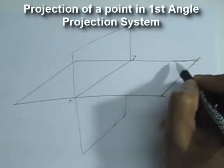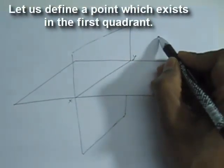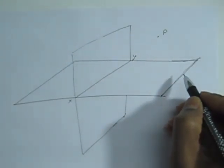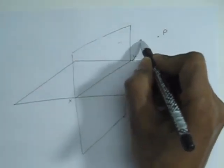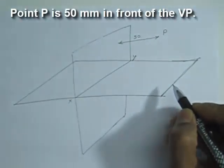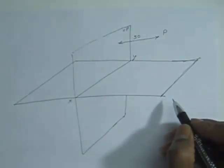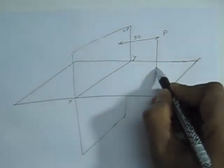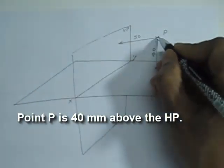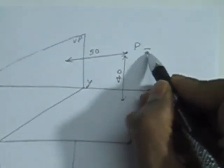Let us see the projection of a point in the first angle projection system. So this is a point, the point P, and this point P is in the first quadrant. It is 50 mm in front of the vertical plane and it is 40 mm above the horizontal plane. So this is the position of point P.